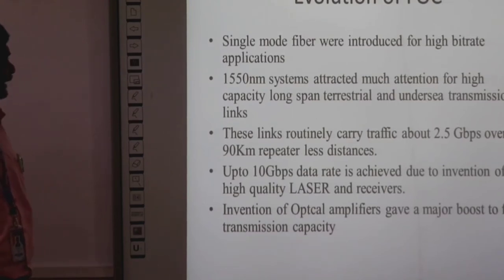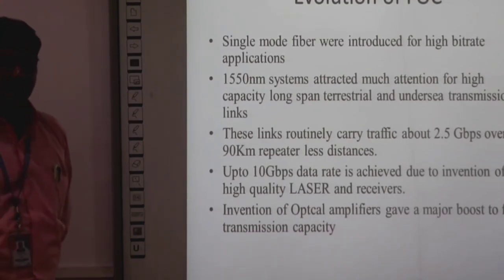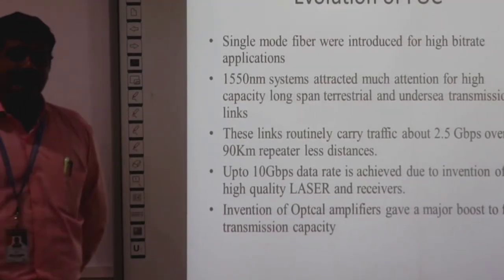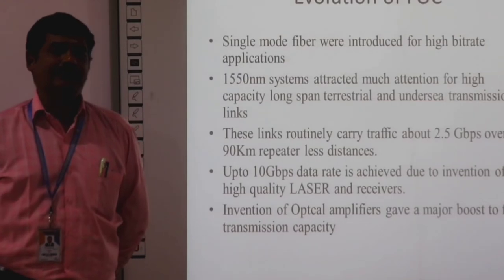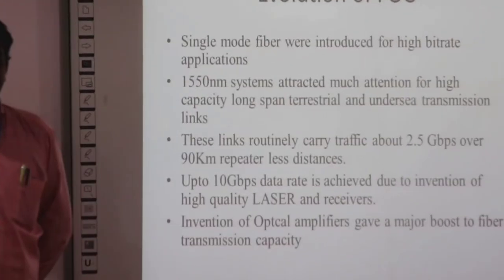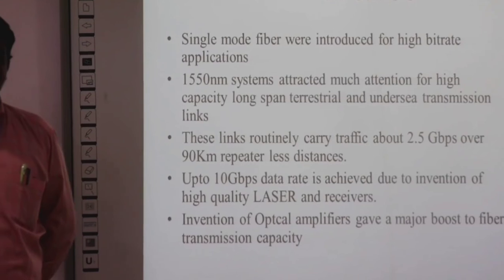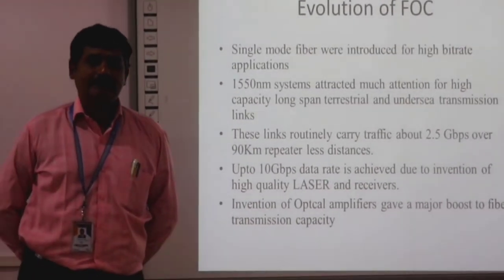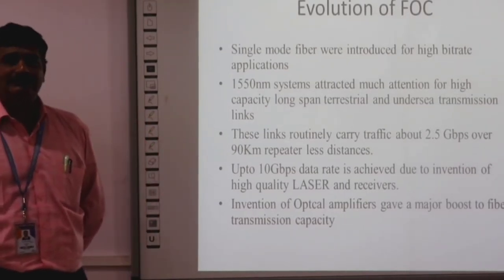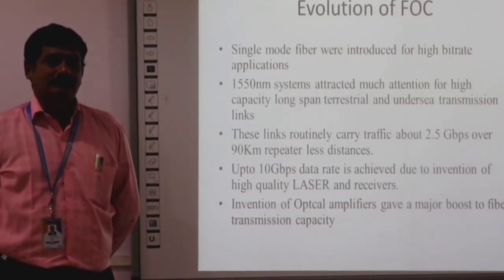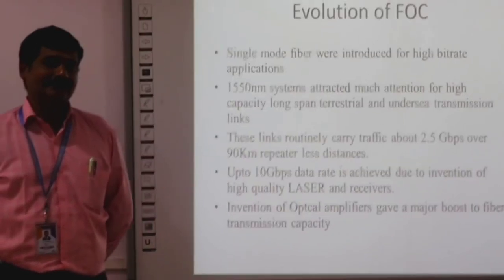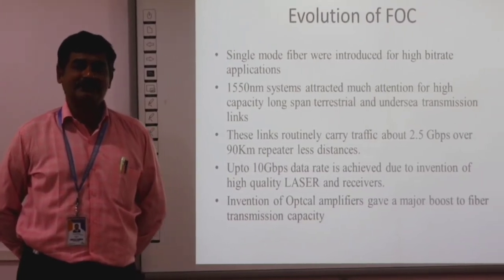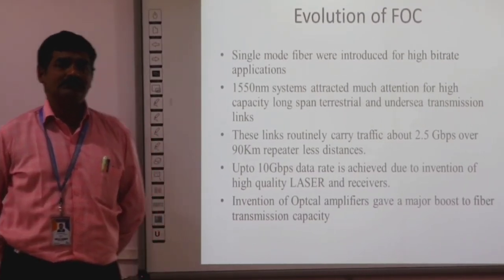Single mode fibers and multi-mode fibers are there. After the invention of high quality lasers, single mode fibers are used for transmission of signals over long distances. Compared to multi-mode fiber, single mode fibers use laser as their source and are used for long distance communication. Multi-mode fibers use LED sources.